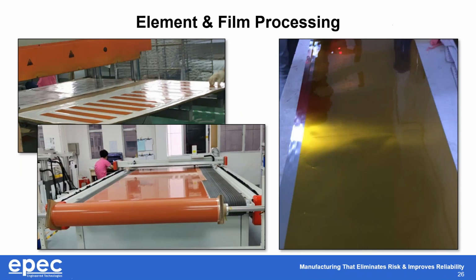This is accomplished because of our manufacturing techniques. We etch our own heating element foils, and we use our own calendared sheet silicone film and completely customize it to shape. By changing the footprint using existing listed materials, you can achieve a completely different shape while the thickness and cross-section may be the same. The different shape, and therefore different wattage or fixed resistance, can all fall within that same UL or CSA listing.